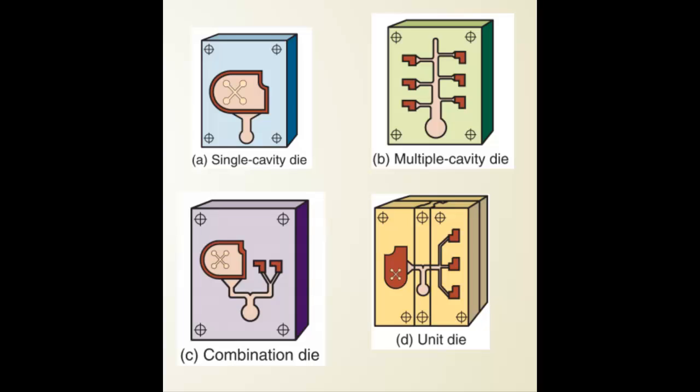Also, all these engine blocks must be connected by a running system to allow the molten aluminum alloy to flow through the pouring basin onto all the cavities. The problem with this will be the time of solidification. If the molten metal solidifies before filling up all the cavities, there is a misrun defect. Not to mention that bigger sand molds will be harder to handle by the robot arms at the foundry.